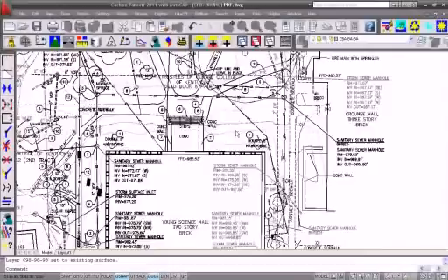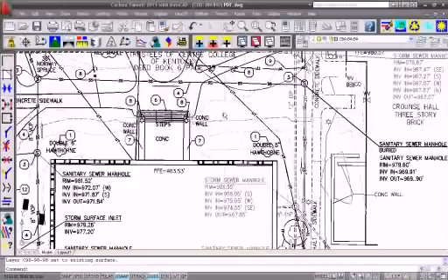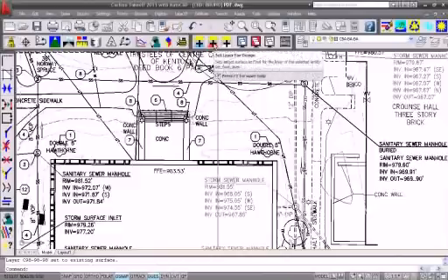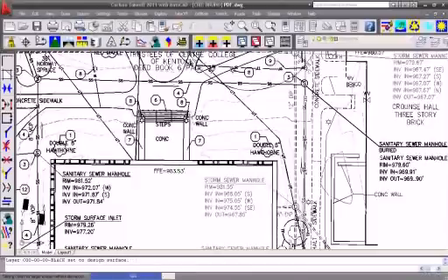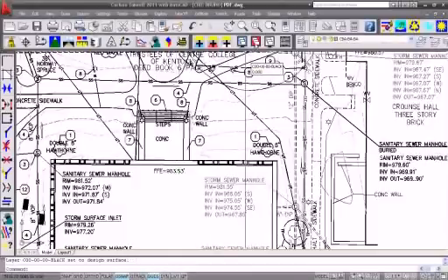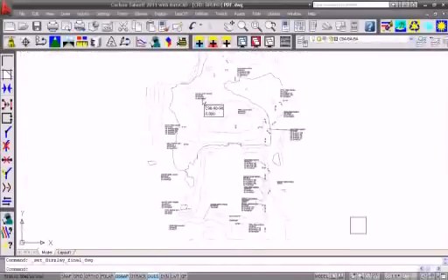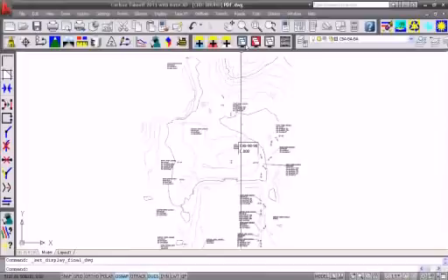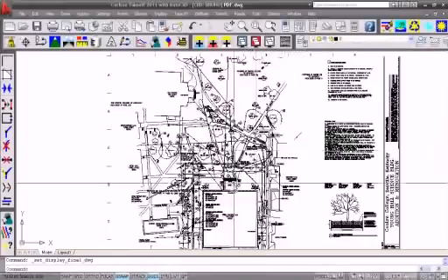Because obviously from that file we need to find out what the existing is and what the proposed is so we can get the differences. Right. So it's important we find which layers, which line work is attributed to which file format, whether it's existing or proposed. Okay. Yep. So I have some line work under existing now, and some line work under the design.